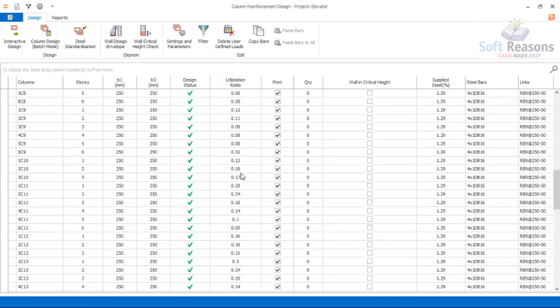Now why we are having this U ratio very much less than 1 is because we did not officially apply wind load. We did not also officially apply earthquake load on this structure. Assuming we officially apply these two loads, you could have seen that even the sections may not necessarily be sufficient. Okay, but this is for the sake of presentations of today.